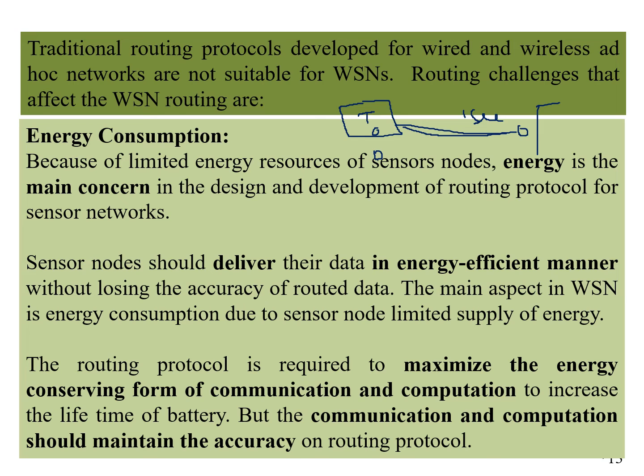So for 1 minute, the gateway will receive 60 readings, because you are getting a temperature value after every second. And the temperature doesn't change in a second. So it is not a good approach to send data every second. And even 1 minute is also not a good approach.